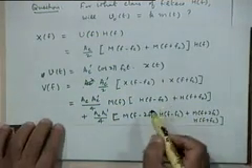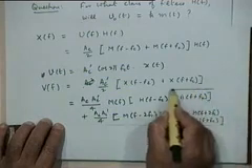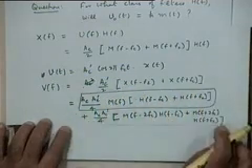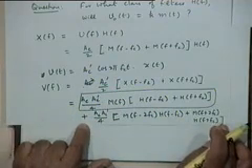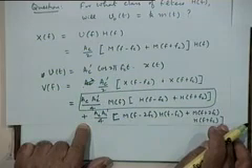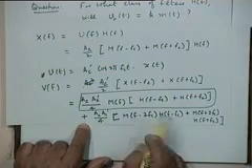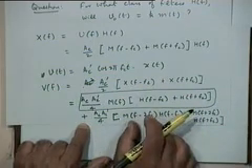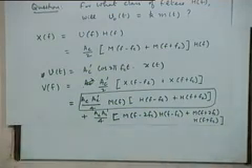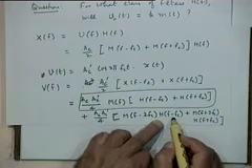So essentially what we are saying is this is the low frequency part of V of F and this is the high frequency part of V of F, which will be centered around 2FC, and you can see that this is obviously centered around 2FC because M of F was a low frequency spectrum, so you are shifting it to 2FC. What about H of F minus FC?